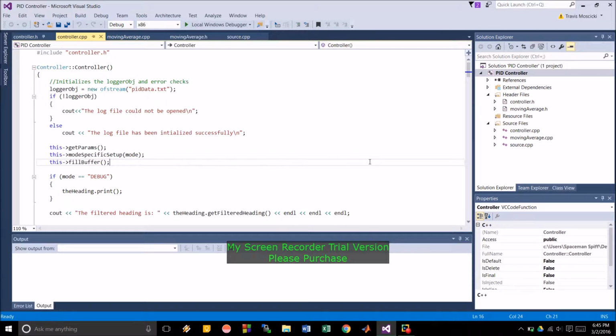This gets a plus sign, and this gets a negative sign, so this is a summing junction. The output of your system gets run back through, probably with some filtering for your sensor suite, and comes into the summing junction. So you have what you want, your desired, minus your actual. This is going to be your error term.